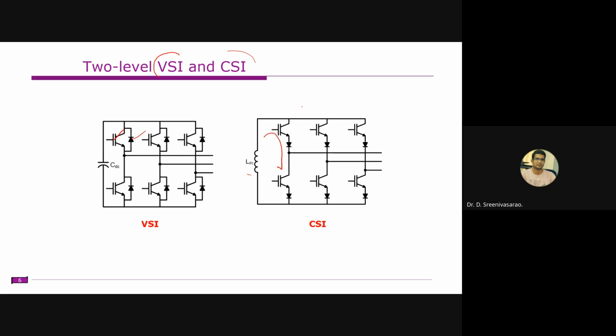So when a dead short circuit occurs across one phase leg, in that case the current will be equal to the source current. Whereas if a short circuit occurs here, since we have a voltage source, the impedance is short there, so theoretically you will get infinite current, and it will damage the switching devices. Obviously, this can be prevented by adjusting the firing pulses between these two, or by maintaining some delay between the upper and the lower devices.